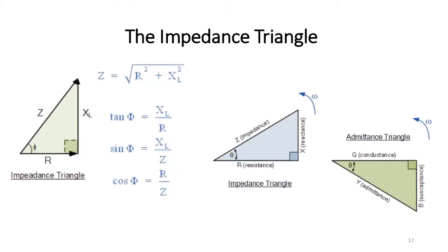So this is just another way to see it. Please read these, for example how to find the impedance. This is the impedance triangle. It's the same concept as power. Look at the resistance and the reactance: when you go up, it's plus X, so this impedance is inductive.